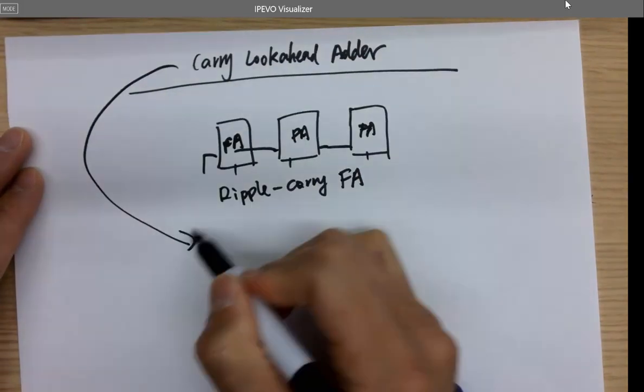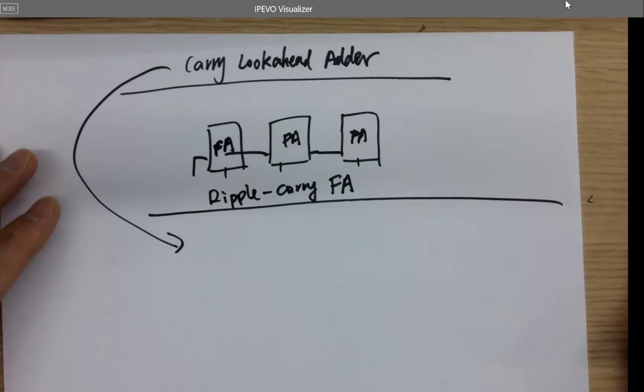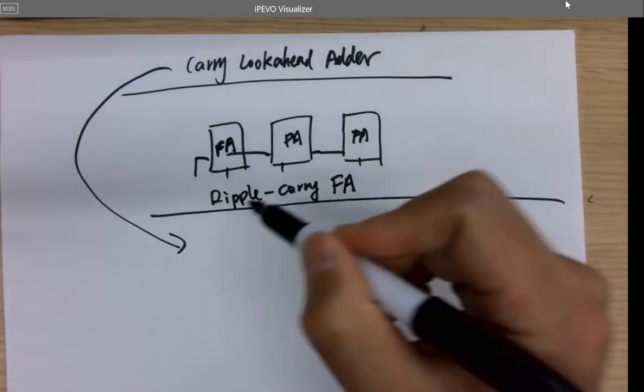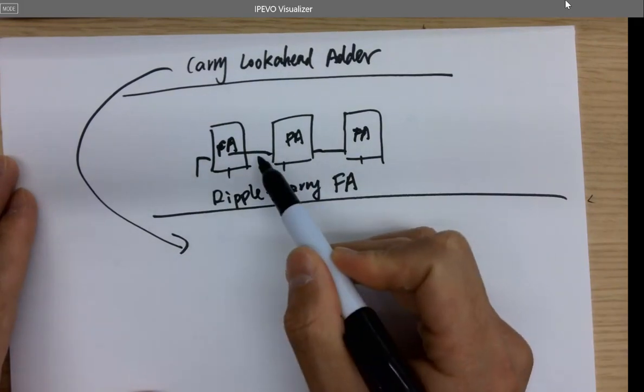So for the carry look-ahead full adder, it's being derived in a different way, but still using the same logic. The advantage of using this one is you can get C2 a little bit faster than the ripple carry full adder. You won't get C2 until you have C1 available, right?